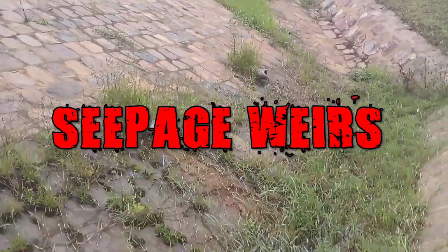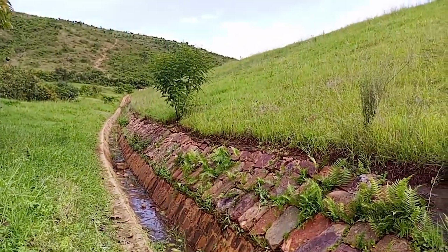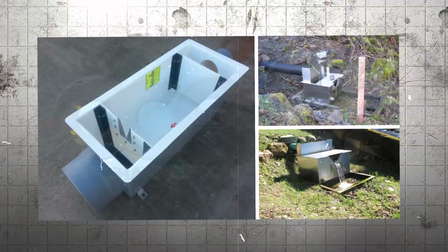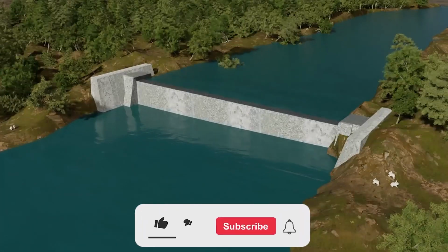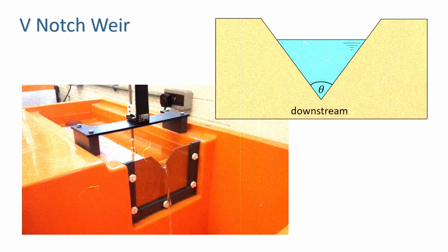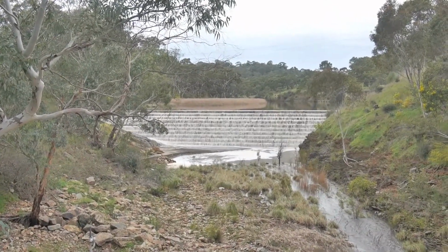Seepage weirs are another thing that can be used to monitor seepage. These weirs are basically just small barriers or walls that are built on the other side of a dam from the water. If there are internal drains in the dam, they help to guide the water towards these weirs. The seepage water collects in front of the weir and then flows over. This helps engineers measure and understand how much water is leaking through the dam. If the flows suddenly increase, this can mean there's a problem.